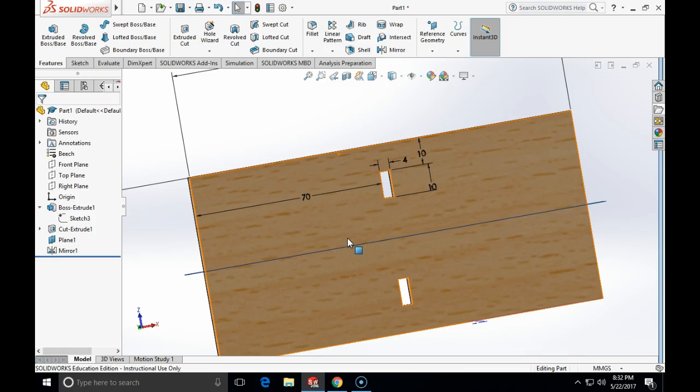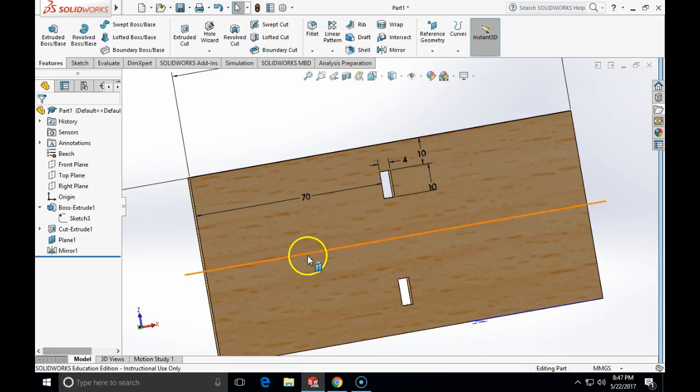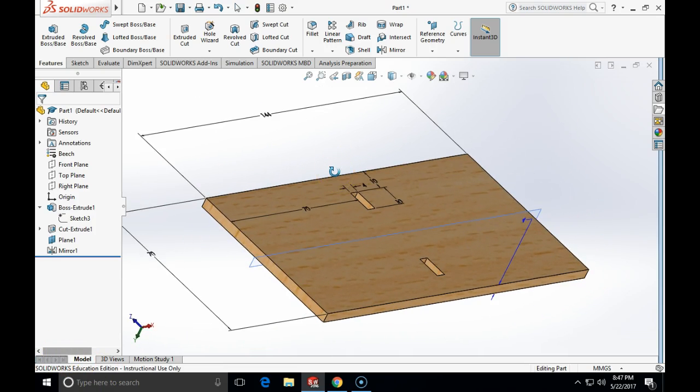So, placed features should always be done in a way that minimizes the number of operations, and if I have a single feature which is replicated, we do use commands which just replicate that feature. One of the simplest is a mirror. There are also arrays and a couple of other commands that we will learn as we progress. This is a demonstration just of the workflow. So do the mirror as I just showed you. With this we have completed our first part.